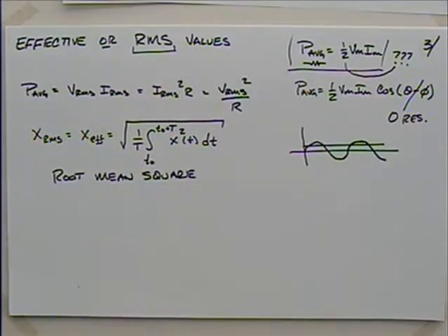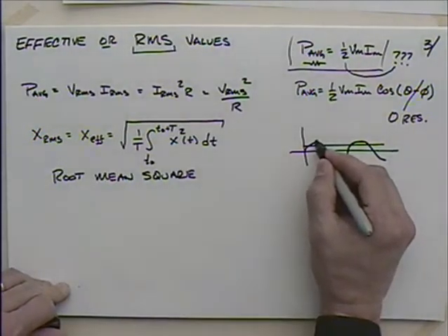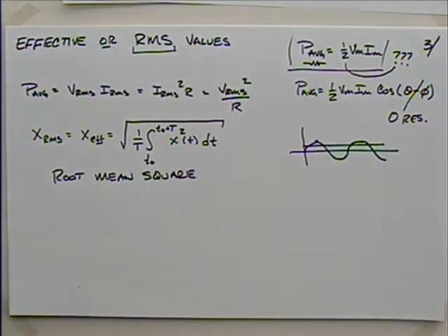That's what RMS is. Okay? And in fact, when we look at the plug on the wall here, and we talk about 110 or 120, that's actually RMS. So the peak value, if you choose to get shocked at that time, is actually larger than 110 or 120. We'll give you the numbers on that in a moment.